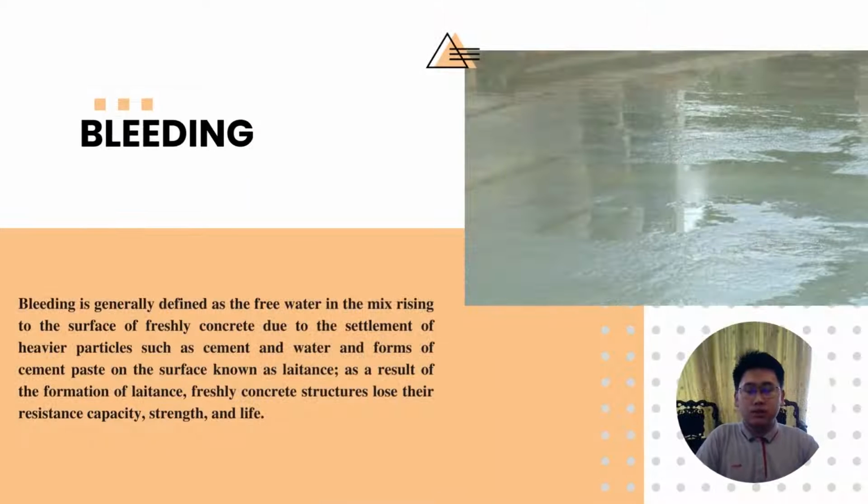The last common root cause of problems in concrete is called bleeding in concrete. What is bleeding in concrete? Bleeding in concrete is generally defined as the free water in the mix rising to the surface of fresh concrete